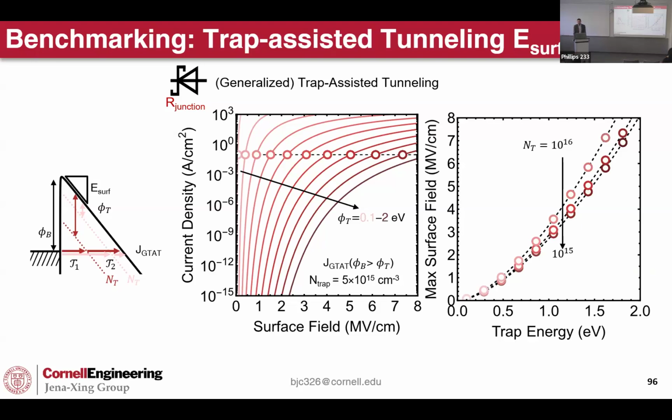But again, if you do your epi carefully, you should have very low values of gallium. So that activation energy is still quite high, even if it's decreasing. Grace and I, and Professor Xing and I, have had some detailed conversations about interpreting the defect kinetics, and that as you're depleting it, you're moving the Fermi level downward. So how does that relate to defect generation? Because now the equilibrium value is increasing because you're depleting it. Of course, you're at low temperature, so relative to kBT it's not that much, but interesting little DFT nuances of how dynamic the system is, because there is, and I'll finish my explanation here.